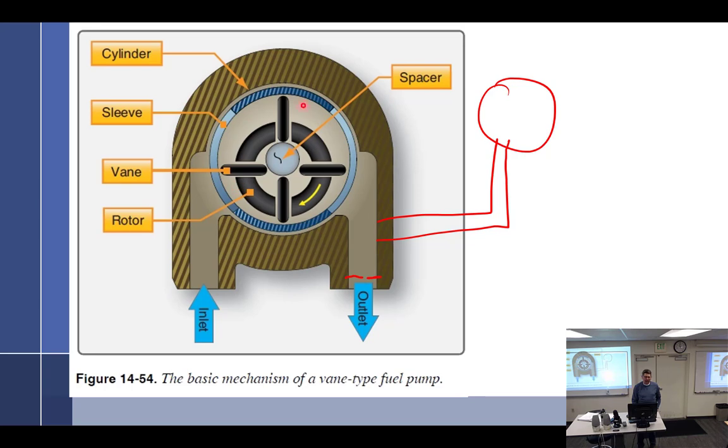Well, this doesn't move very fast. It's going to start moving slow at the starter, kind of slowly work its way through, and it would actually eventually work, provided your battery didn't die first. Or a starter. Yeah, we're going to build a starter. And a lot of these engines, because all the fuel injection lines are on top of the cylinders, if you shut it down, you're going to get vapor lock up in those lines.